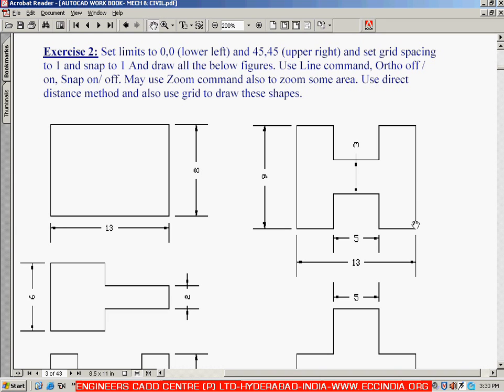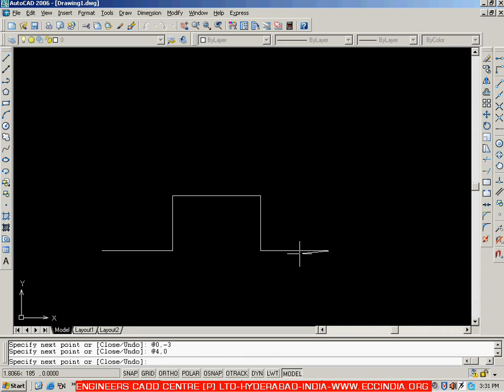Then now we will try to create this vertical line by specifying the top vertices. Now here at this vertex, at this point, let me specify the coordinate values as 0, 9, because now I am standing here, so this is the origin. Then this point coordinates will become 0, 9. So @ 0, 9.